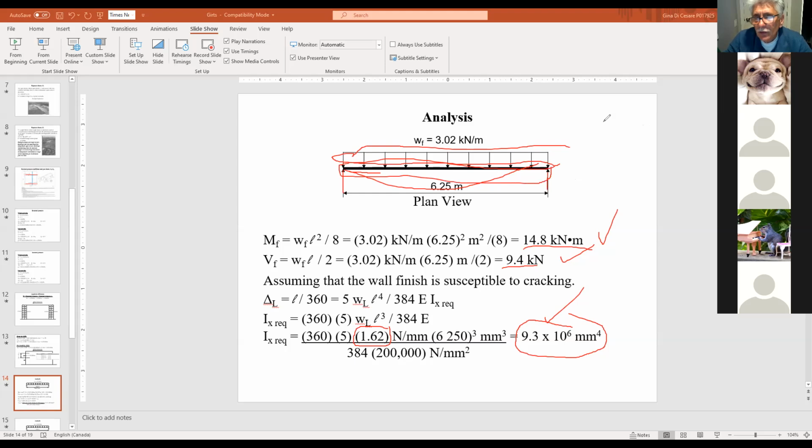What we tend to use for these girts, you have two choices. The most typical shape is what they call cold form channels. They look like this. Or, in the old days before we had cold form channels, we can use regular channels. Since you don't have the tables for cold form channels, we're just going to look for regular channels.